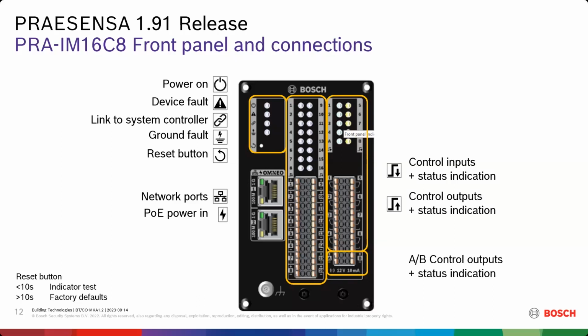So for the reset button, if you activate it below 10 seconds, it will act like an indicator test, so the LEDs start blinking. If you press it more than 10 seconds, then you bring this device back to factory defaults. This means that it will lose the encryption key and that you need to reassign the device to the system. All LEDs blinking indeed means then that it is in the identification mode.